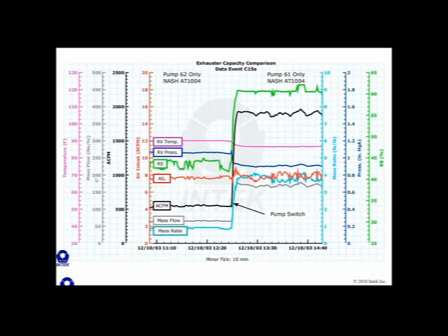Okay, got an answer, good, yep. It's less than 3 here, right? It's less than 3 for pump 62. Yeah, there we go. Okay, so somebody's hit the nail on the head right there. So pump 62 is not good. Pump 61 is good. So how did he come to that conclusion? Water to air mass ratio is low on pump 62. Water to air mass ratio is high on pump 61.